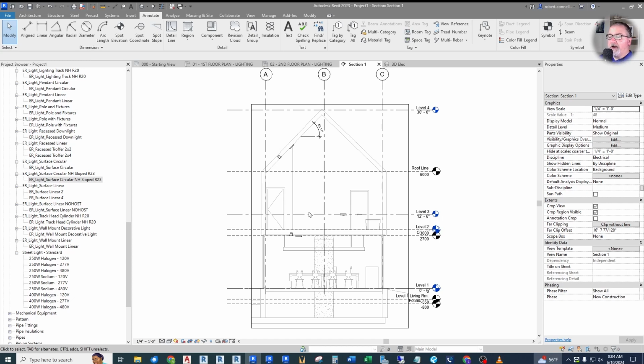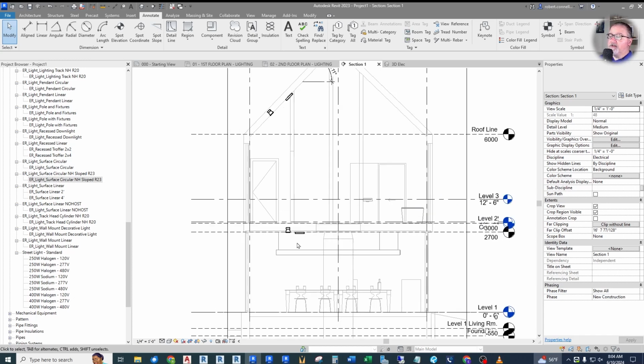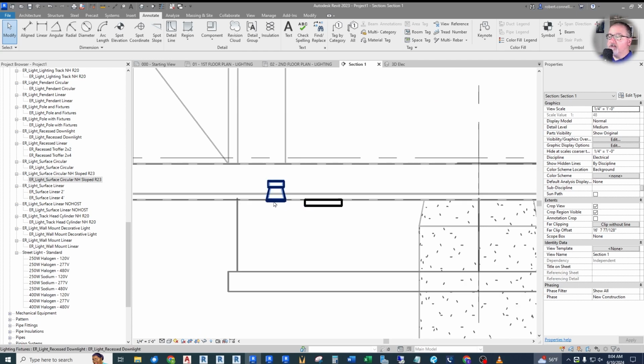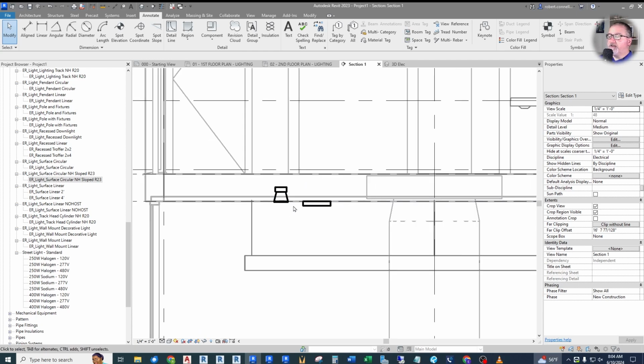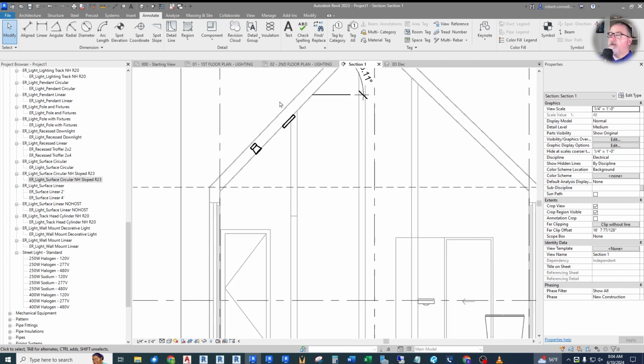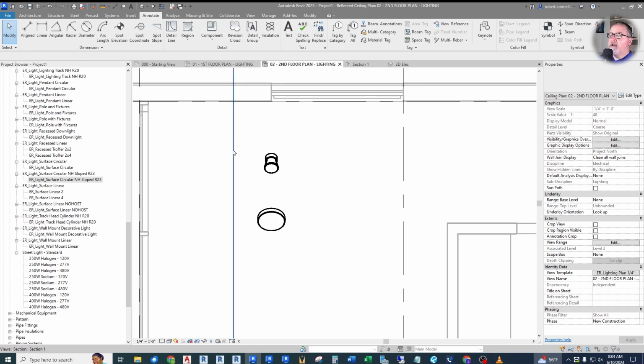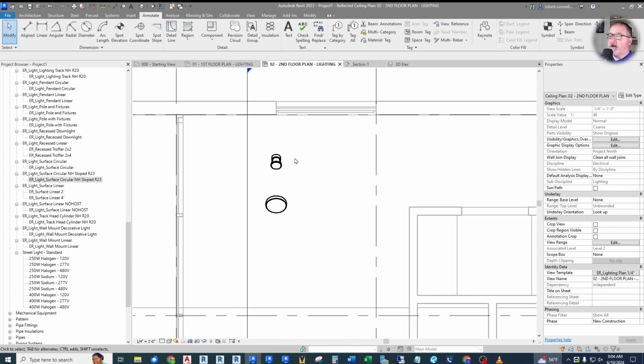Have you ever been working in your Revit electrical project and you insert light fixtures that are hosted, and they look great on a flat level ceiling, a recessed fixture, a surface fixture, but then you put them on a slope ceiling, they look great here, but when you look at plan view, you get this weird skewed kind of fixture look to it and there's no symbol, it doesn't show up properly.